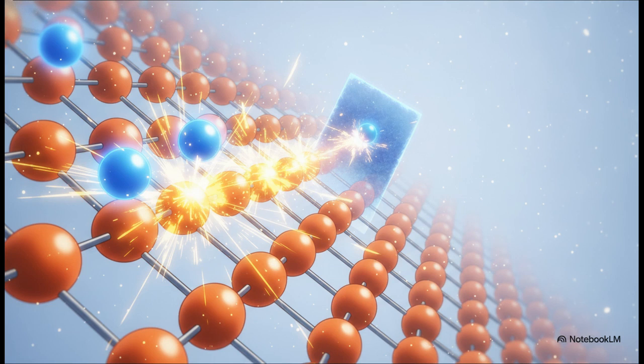Well, at high current densities, the electrons traveling through the wires start violently colliding with the atomic lattice of the material itself. This generates localized vibrations, essentially heat waves, which we call phonons. We know this as Joule heating. Those phonons act like a really chaotic, dense crowd that the electrons have to fight their way through, and that physically increases the material's resistivity.